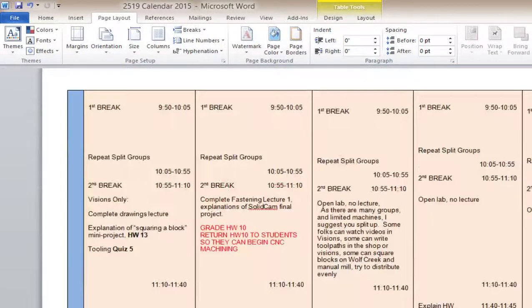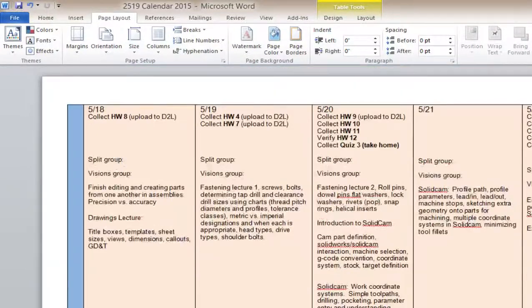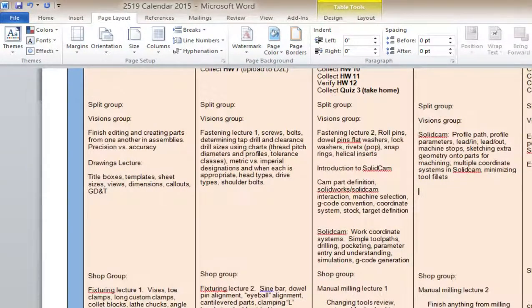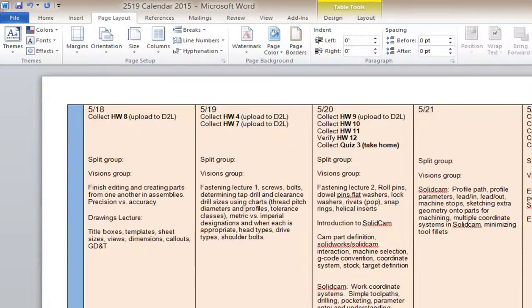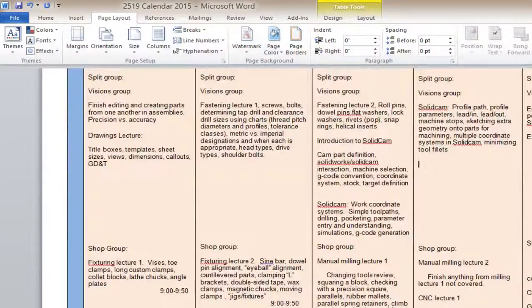So can I add something to that? I didn't show you guys drilling and reaming on the machine. Remember from my lectures, the spindle speed for the reamer relative to the spindle speed for the drill, what was it? Half or lower, really. So I didn't show you that, but try it out, and somebody will be around to help you if you need it. Okay. And there'll probably be more lecture tomorrow, right? Yes. I can actually show you a range hole tomorrow, first thing.